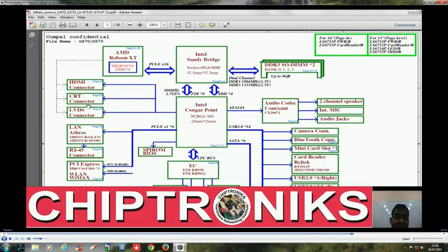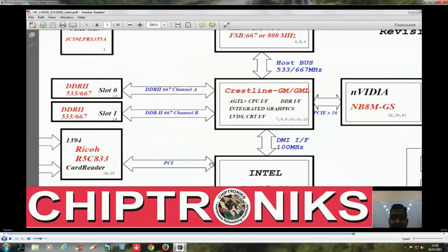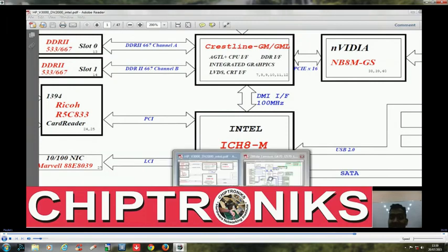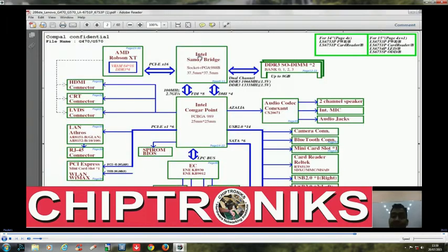In that case, the output connectors are directly connected to the graphic chip. And DMI, as we know, you check here in DV2000, was a dedicated connection between GMCH and ICH. Here, as we said, the memory controller has moved to the CPU.